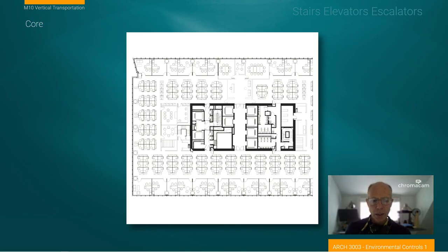So in this case, we see these thickened walls around the exterior of it. We see doorways containing the hallways for these egress methods. And in this case, these are elevator cores. Some of these are remotely located, which means they may be for service or private alternate access to floors. And some of these are in this public area. So we have 6 elevators in this public access area. They've also chosen, in this idea of the core of the building, to locate the bathroom facilities. But this is a stiffened core in the center of the building.